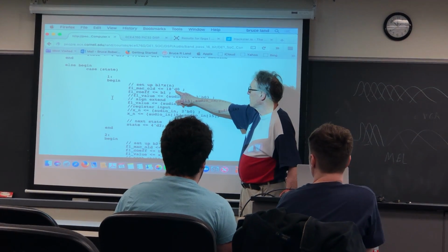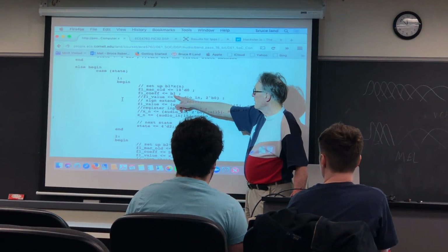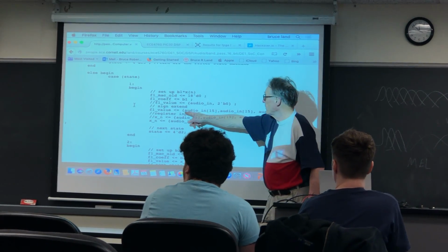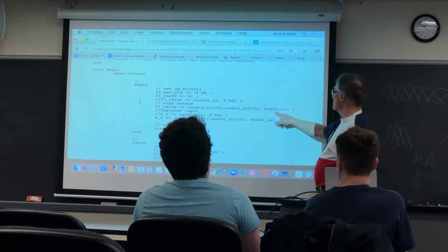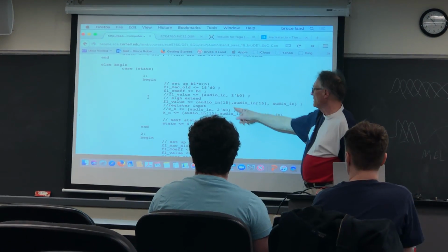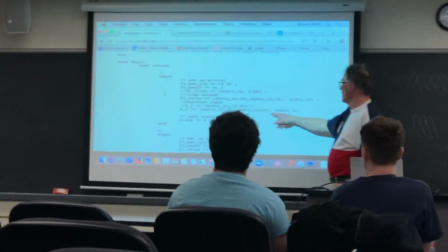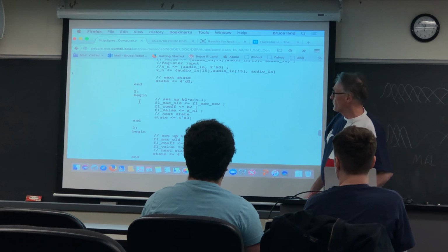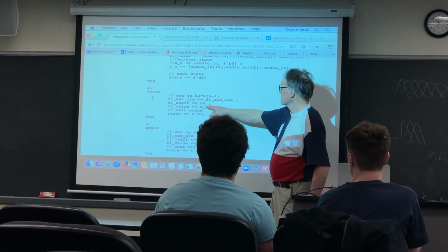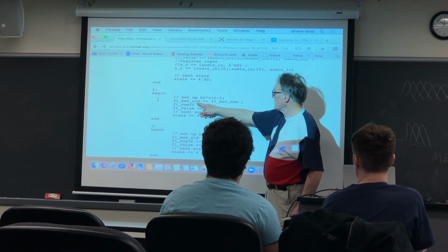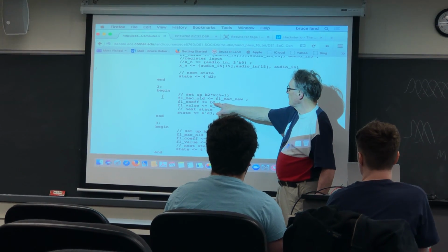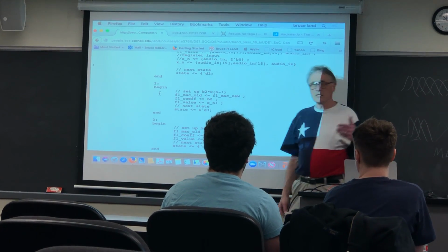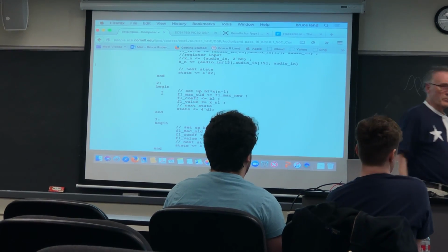So we zero the old MAC value. We retrieve the B1 coefficient. We take the F1 value, the first sample value, use the audio in, which is 16 bits, sign extended to 18 bits, and also copy it to XN because we need it for another value. Then go to the second state, where we take the new MAC value, put it into the old MAC, set the coefficient to B2, set the F1 value to X minus 1, go to the next state, and just step through, doing each multiply and accumulate, one per step.